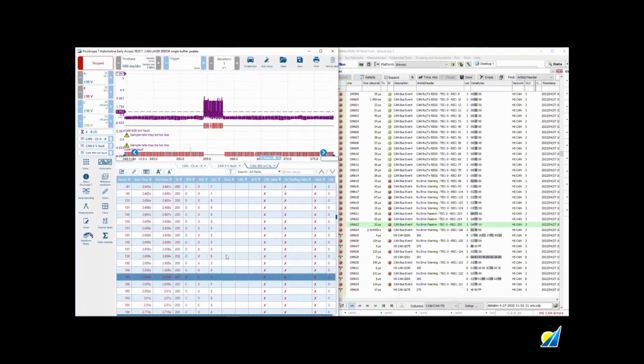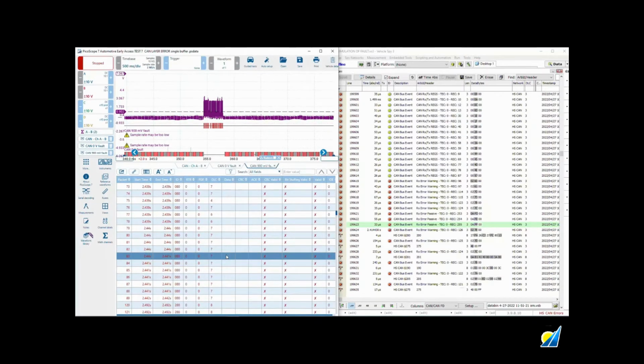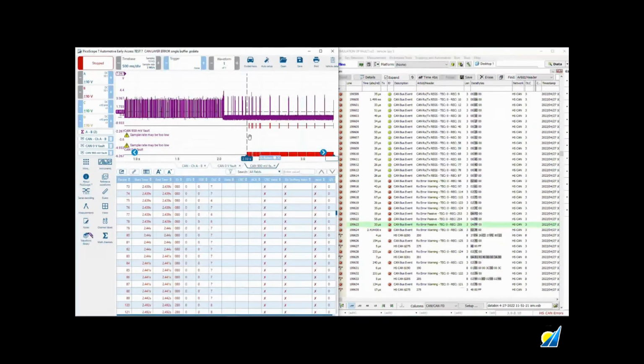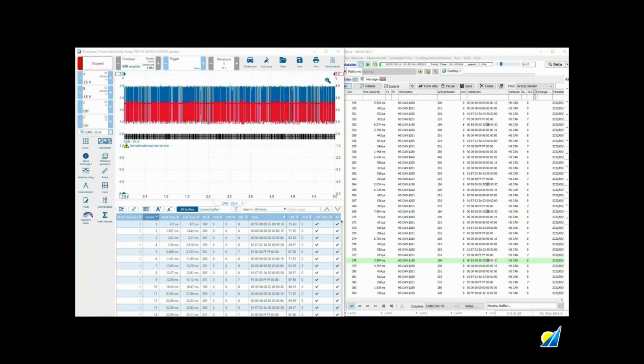So there are 3 IDs that are trying to communicate during the fault condition, which certainly suggests they're not offline at that point in time. So food for thought there, and maybe further diagnostic information. Going back to those previous captures, it would appear that transmission was ongoing during the fault condition, and we'd identified a number of IDs: 80, 200, 275 and 280.